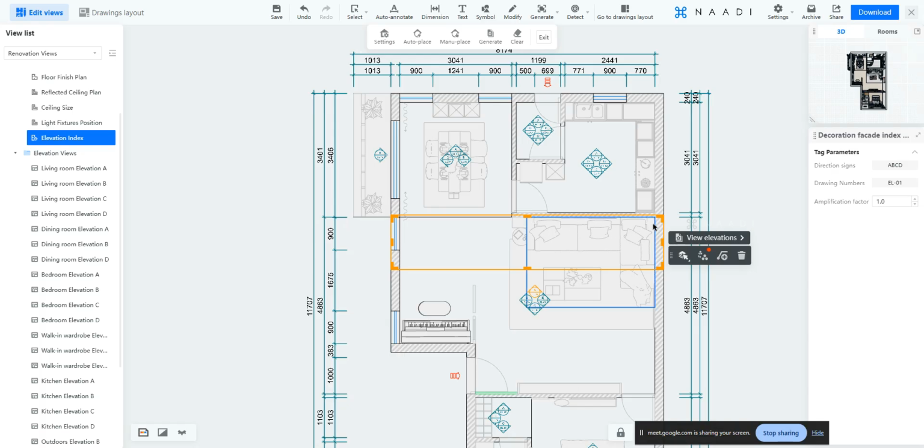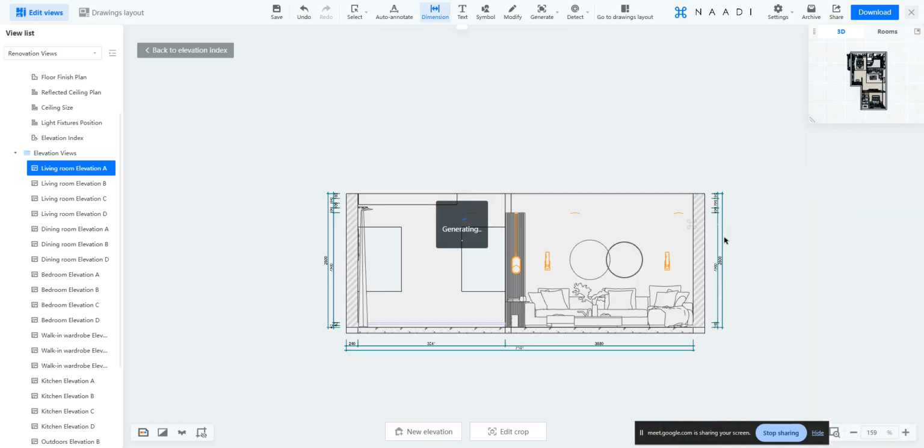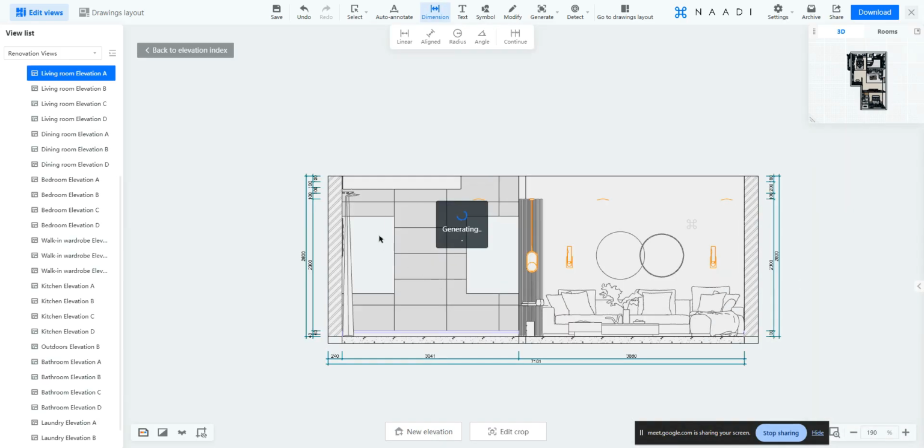Say, if I set it here, this is the boundary. Till this part, I will see it in the elevation, and that is the reason why this space was empty, because there isn't anything in this region. If I want to see this wall, then extend this elevation till this wall here, the farthest point of that elevation boundary till that point. And now if I go to the view elevation tab here, you will see that wall, window and everything as a part of that elevation.